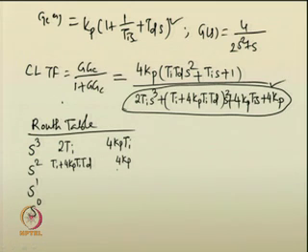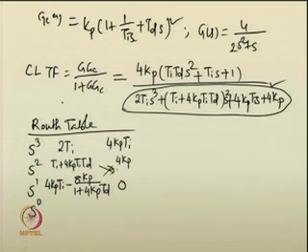Now, the next coefficient can be expressed as 4 Kp Ti minus 8 Kp upon 1 plus 4 Kp Td, and this is 0. Then the cross multiplication like this and this divided by this will give us 4 Kp as the coefficient of the last row.